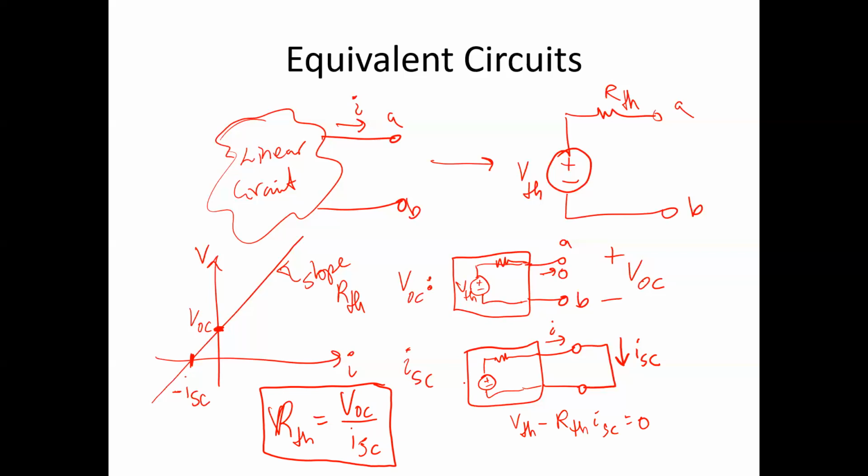The last kind of measurement that we usually need to make when we're dealing with equivalent circuits is the idea of the test voltage. And the idea there simply is, again, let's take our Thevenin circuit and let's add the test voltage. So again, here you have to make sure that it's connected like this, VT, and IT is coming out of the positive end in this case. You'll see why that needs to be the case shortly.